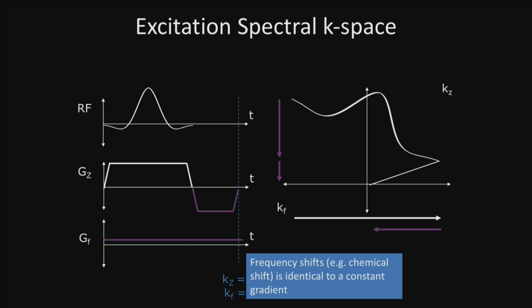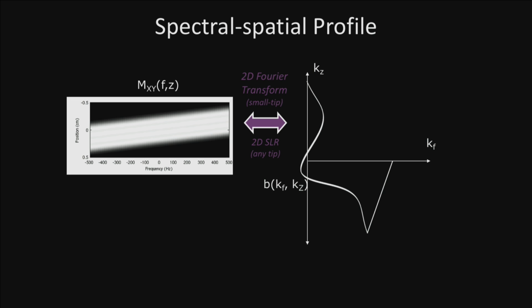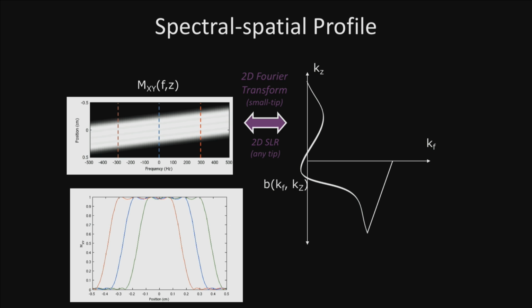And this was actually a very simple pulse. This is our slice-selective RF pulse, right? And even from this very simple pulse, we can glean a couple of things from this example. Here we have some slice thickness, and if I plot this as a function across position at a few different frequencies, we'll see that we select a slice, like I showed earlier in the talk.